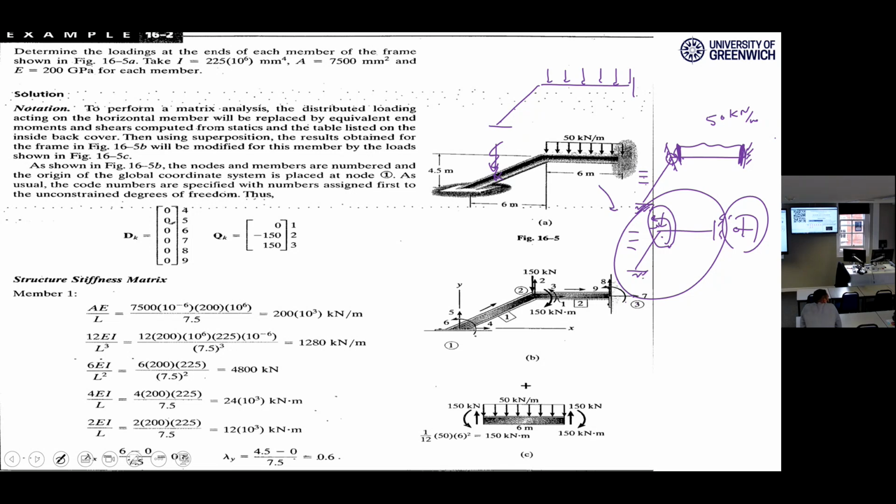They are there. For example, you have a cantilever, this structure, like here. Okay. Question. I push this support. What happens? Can I analyze this structure without this pushing and just keep it to the end? Yes, I can. But this push doesn't produce any deflection in this beam. This is just applied to the support. See, this is a wall. If I push this wall, nothing happens. It just pushes back. If you put a force on a support, nothing happens in the structure.